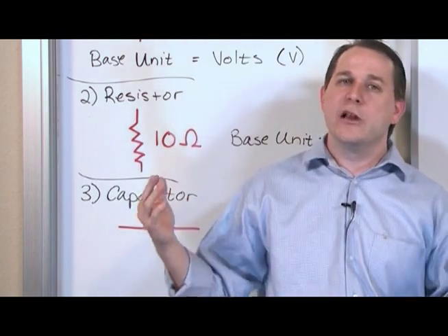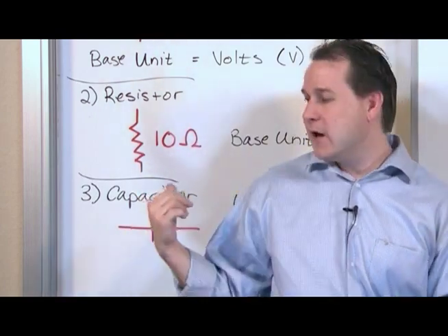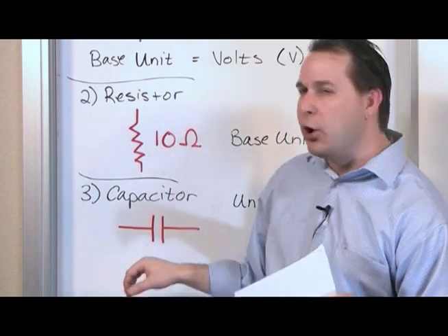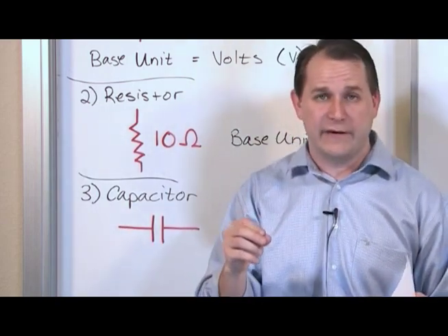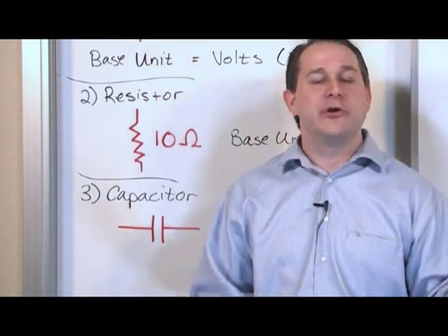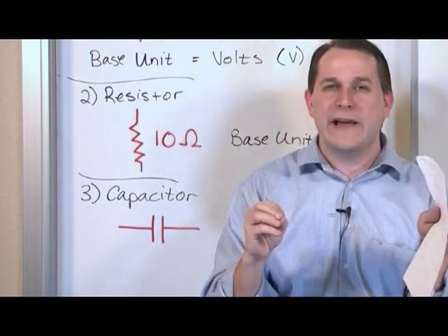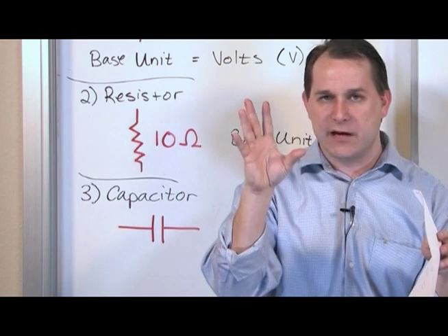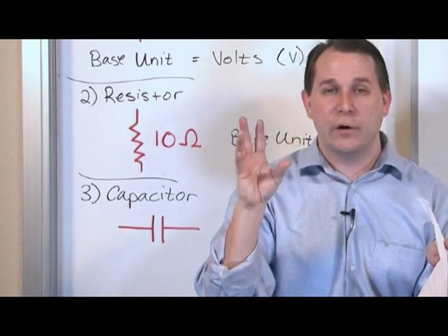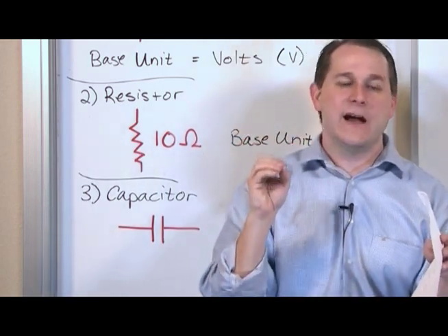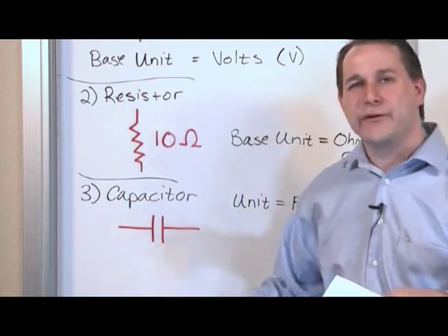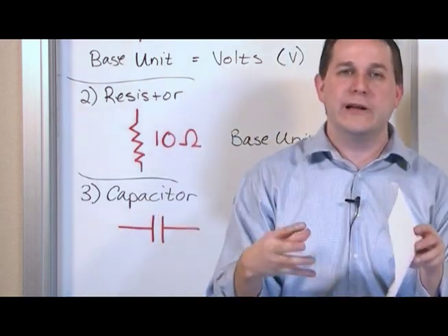What's going on there is a lot of electric charge is coming in from the battery and filling up a whole bunch of capacitors. There are a lot of capacitors in there, and they're wired up together. And they're charging those capacitors, getting them really, really charged. And then notice on your camera, it takes a few seconds for that light to come on to tell you, all right, ready to go with the flash. That light takes time to charge up because these capacitors take time to actually accumulate this charge.